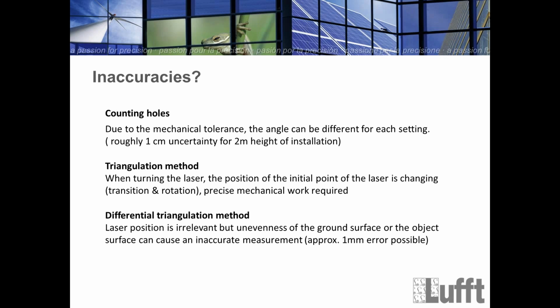In case you have a flat surface where you can put, for example, the cover on it, it is maybe best to use the third method, because you don't need this correction factor anymore, and you can reach millimeter precision if you can do this kind of measurement, quite precise. So that should be fine.